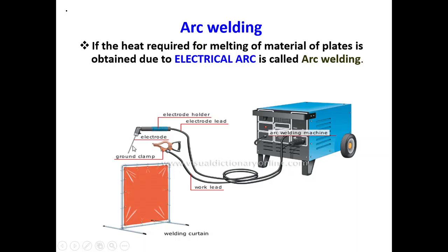First, regarding the electrode. These are classified as consumable and non-consumable electrodes. Consumable electrodes provide the filler metal in arc welding. They are available in the form of rods or sticks and wire. These rods are 9.5 mm or less in diameter, and have a length of 225 mm to 450 mm.